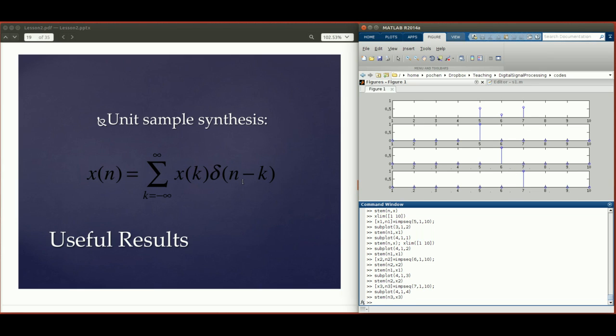The amount of shift is the location where the input signal x[n] has non-zero amplitudes: 5, 6, and 7. You construct a shifted impulse at those locations where x is non-zero. If x is 0 at a location, for example location 2, the weight for that shifted pulse is 0, so it doesn't contribute to the final summation.